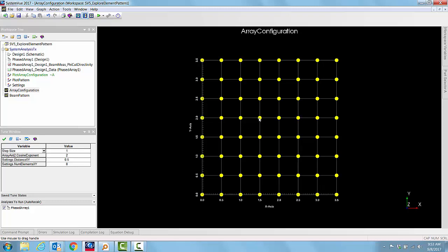But in reality, all the elements in a phased array are excited simultaneously. If we excite all of them and measure the reflected energy at the input of this antenna due to mismatch, the energy coming back at the input is not only because of the reflection due to mismatch, but also because of the energy this element picked up from the other radiators in the surrounding.